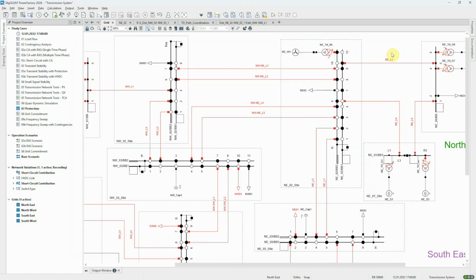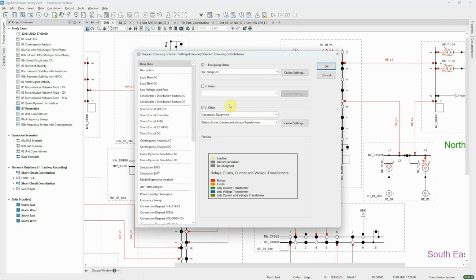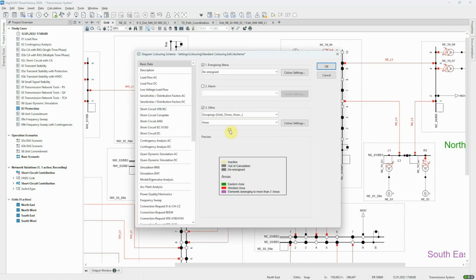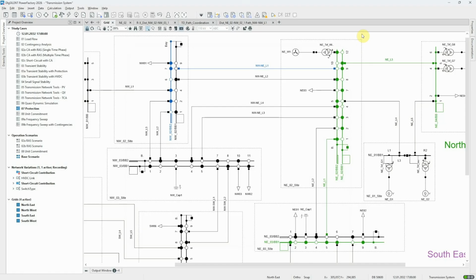In general, a good way to look at the settings that have been calculated using the Protection Coordination Assistant is to create a time-distance diagram of a defined path. In this example, there's already a simple path defined, which you can see by changing the diagram coloring to Groupings, Paths. The path includes four devices for which we calculated the reach settings.